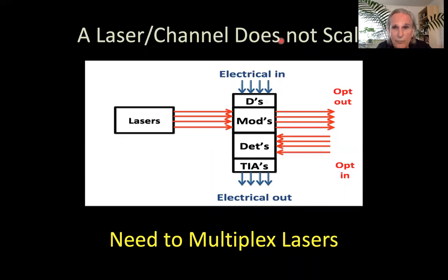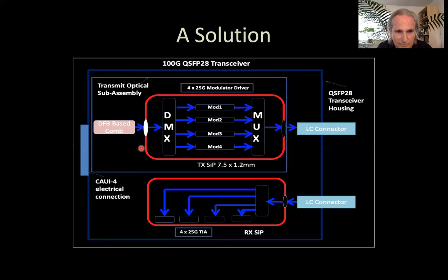A big problem with all of this would be just the sheer number of lasers if you were using a laser per channel, like 48 times 48, and you're going to start needing hundreds and hundreds of lasers. All those lasers need power supplies. They all aren't the same. You'd like to minimize the number of sources, de-mux the sources, maybe put a few optical amplifiers in there, but have a handful of lasers and a handful of optical amplifiers off chip in order to do this. And that is a big research area.